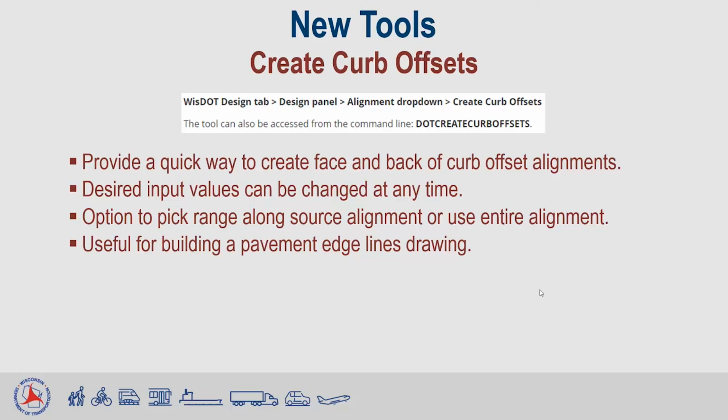on our plan sheets. So this is really a tool you're probably going to use a lot when you're making your edge lines, your pavement edge lines drawing. You data reference in your curb flange line alignments, and then you use this tool to create those offsets. Let's do a quick demo of this one since it's our last one.